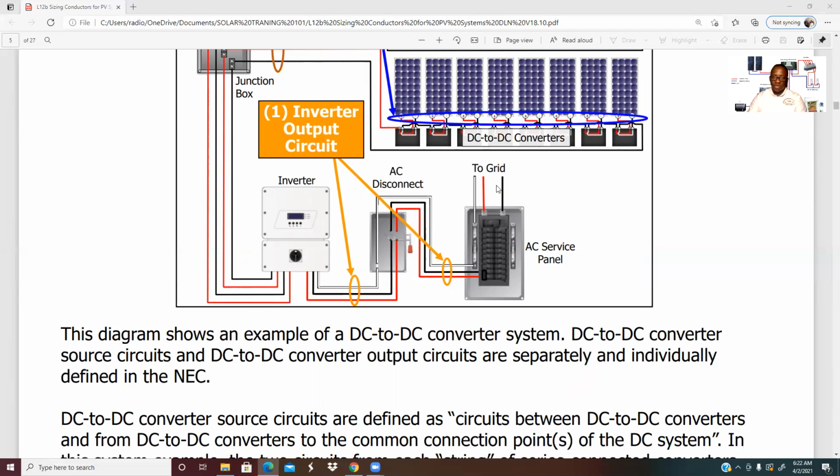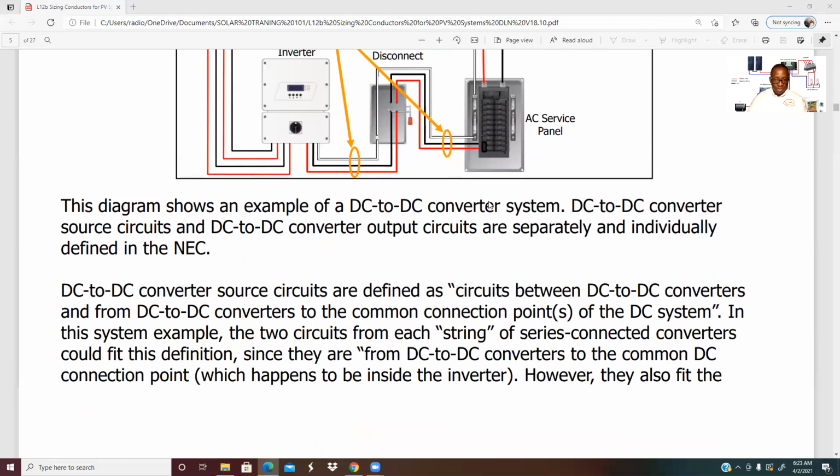When in the day you are getting enough power from the sun, your meter will read backward. So you will be selling current to the grid. And then in the evening, when the sun goes down, the meter reads forward. So then your accessories, your appliances will now be powered from the grid. That's how it works. There's no battery in here. There's no charge controller.